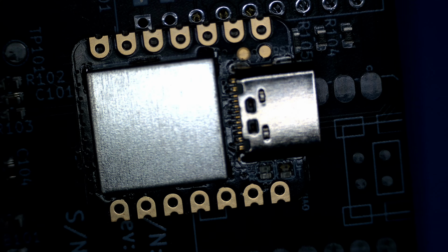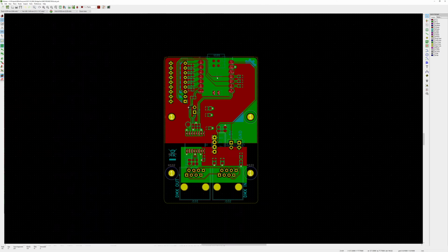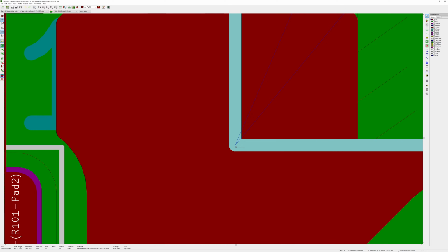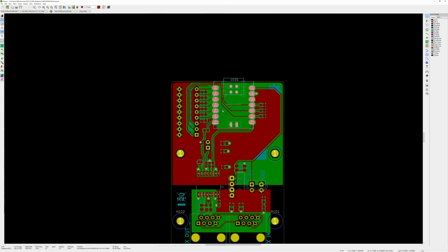And you might say, well, how could it place it so far off? Well, I have a feeling I can tell you. If we come back in CAD and we click on this footprint, you can see the origin of this footprint is that bottom left corner. And what the pick and place machine is expecting is that the center of the footprint will be the centroid of that component. And so the offset that we're seeing in the placement is the offset from the center of the part to that bottom corner, that 0, 0 reference for that footprint.